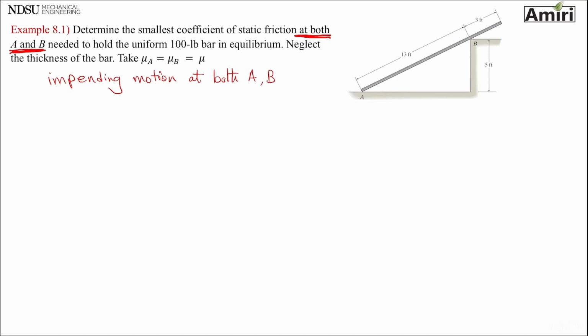Now I got to draw a free body diagram. First step. So let's see. Step 1, free body diagram, is drawing the outline of the shape. I'm drawing free body diagram of beam AB, or AC, whatever it's called. This is the outline. Then put active forces. The only active force that I have is the weight, which I put in the center.